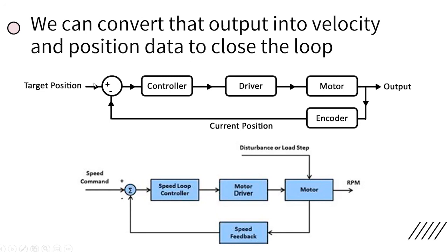And then similarly, let's say I wanted this thing to move 1 meter like before. Then I'm measuring the position and I find, okay, we've hit 0.9 meters. Maybe I should slow down and get ready to brake. Or maybe I've overshot. Maybe I read 1.1 meters. Well, in that situation, I know that, okay, I went too far. I have to back up and get to the right spot. So by using these encoders, we're able to get a much better understanding of what our robot is doing and how we can correct when things are going wrong.